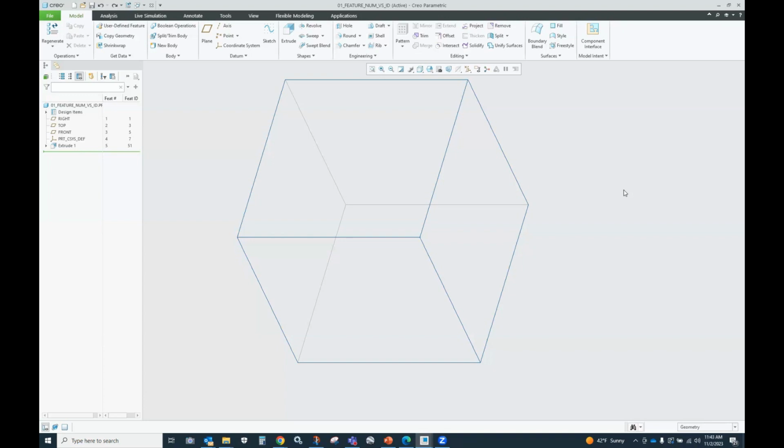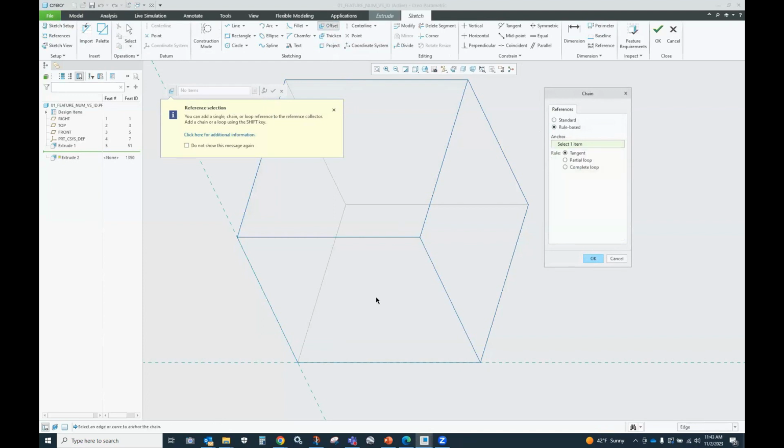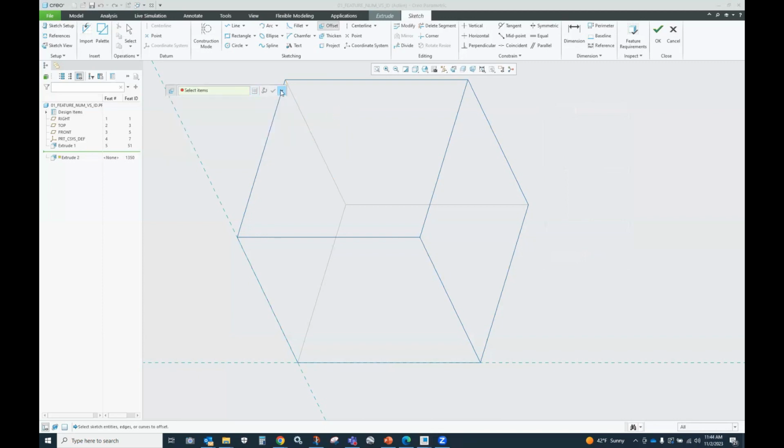Yeah, it did. I'm not using 9 or 10. I didn't know that use edge or project puts up a different menu, but I see where they still kept the loop command. So thank you. Right, it's still there. I think with the offset, it actually has an option to use all curves in a sketch, right? So if I do that one more time, we'll say extrude on there, offset, and we'll go to that list and rules. Oh, not in this case, but this actually will give you a different list in some situations, right? So if you get into Creo 9, look there on this options to see what you can get.